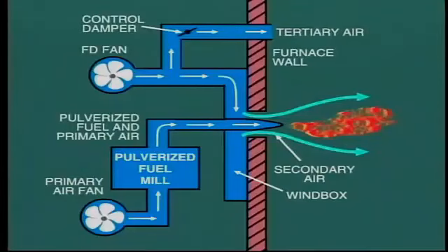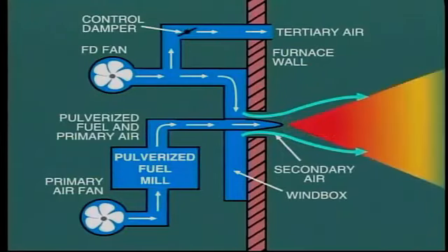In this situation, we run the risk of the fire self-extinguishing at certain burners and then probably reigniting again, so creating a minor explosion or puff, as it is known. In order to maintain stability of combustion at low loads, it is usual to light the startup oil guns. These may be designed to burn diesel oil or heavy fuel oil in some cases. The objective is to ensure that ignition is maintained.